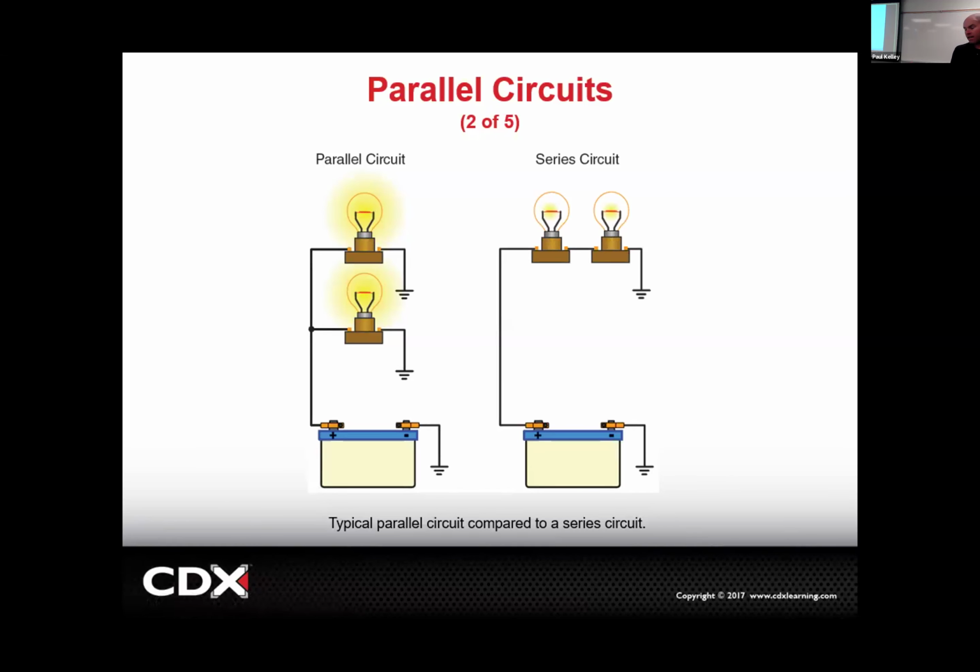So if you want to do it legit, if you want to add 2 more branches, you may very well have to double this wire size on the freeway to support that. Now, you could calculate it, and I'll show you the calculation. But that's the idea. If it's series, you can't just keep adding extra branches because you're going to increase the amps in this part.